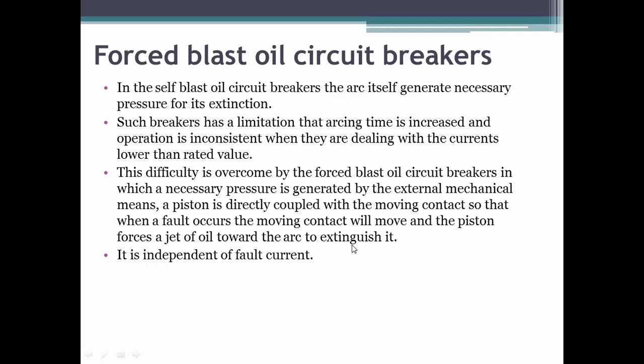So when the self blast circuit breakers are operating at a lower value than the rated current, that time this is taking some time. Okay, means the arcing time will be increased and the operation is not consistent. Okay, it is not consistent. So this is the drawback or one limitation of the self blast circuit breakers.